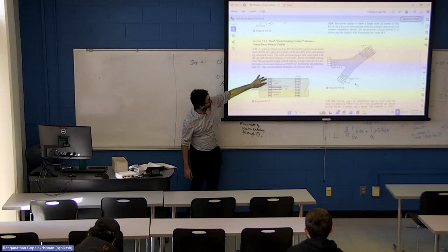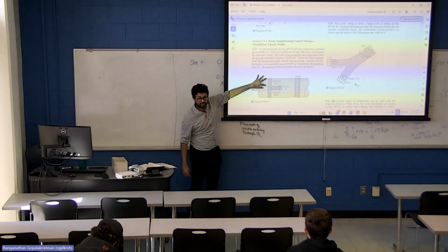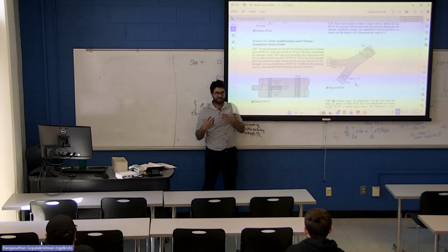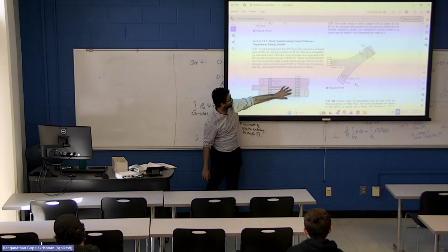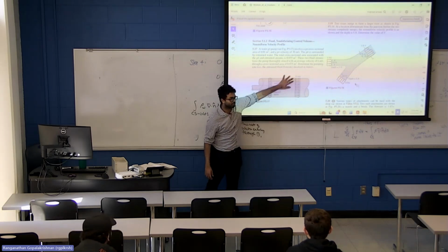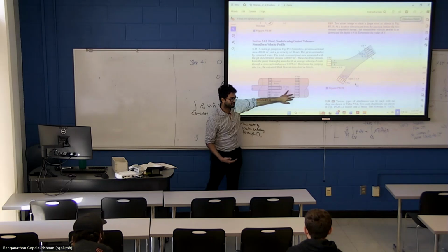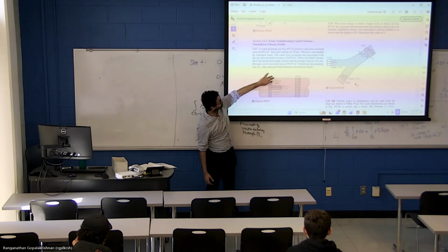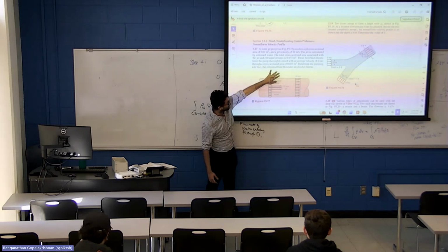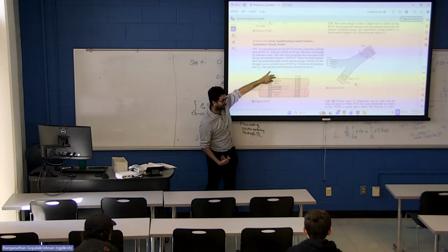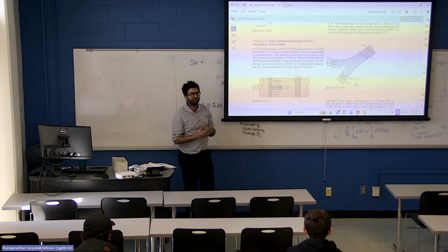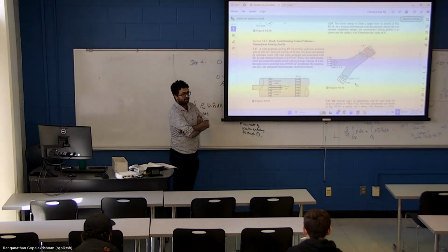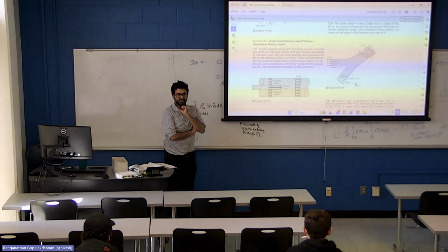Okay, so we need to figure out what's the velocity of the periphery or the entrained flow. What we are told is a little bit downstream, the faster and the slower streams mix together and result in an average of 6 meters per second that's uniform across the cross section. So the question is, what is the velocity of the entrained water? I mean, they are asking flow rate, but first we'll start with velocity and then later get flow rate. Any thoughts? How would we think about this? What should be your control volume? Let's make that selection first.